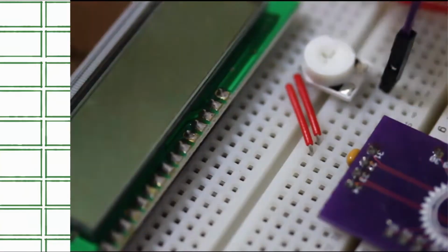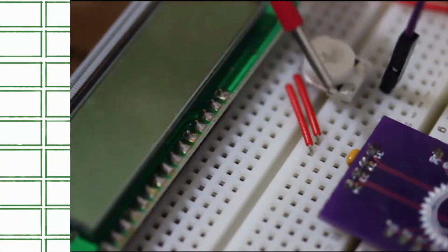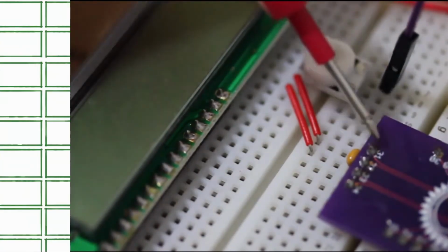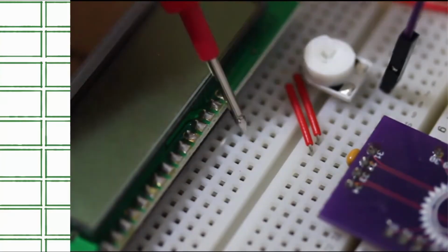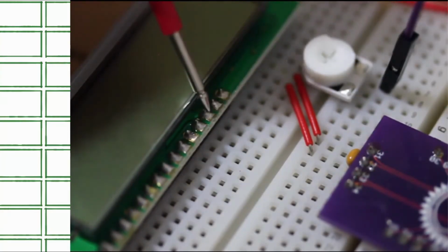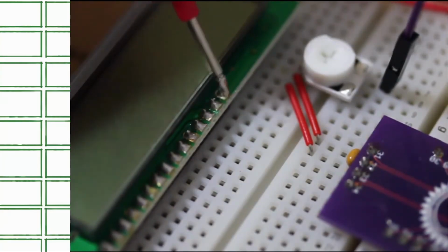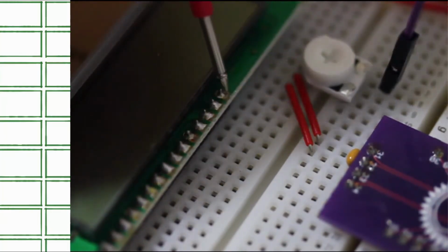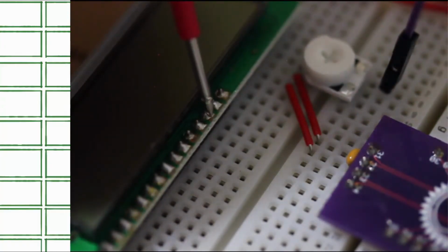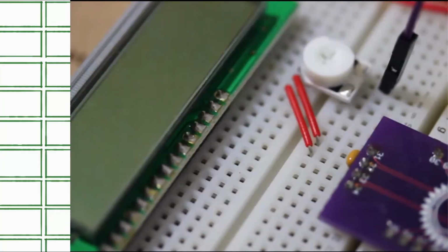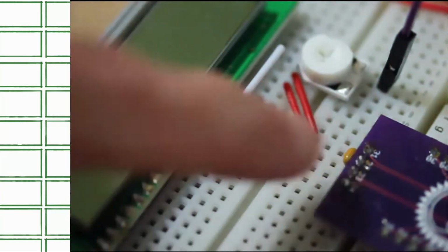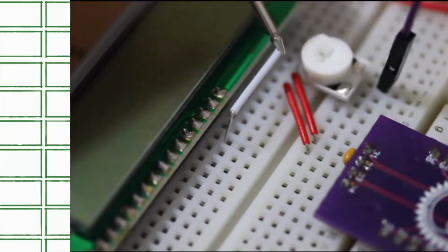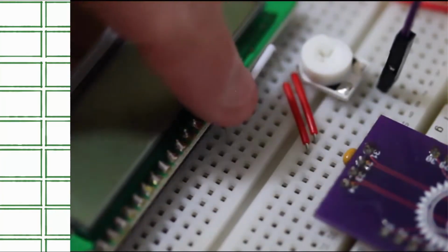Before I connect the power 5 volts to the LCD, I'm going to connect the ground coming from 31. I'm going to connect this ground to the ground of the LCD so I know where the first pin is that we need to use, because these two are not connected and this can confuse me on where to start, because I often think that this is the VSS pin or the ground pin, but the third pin is actually the real ground pin.